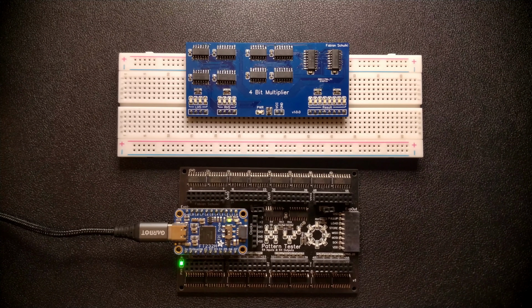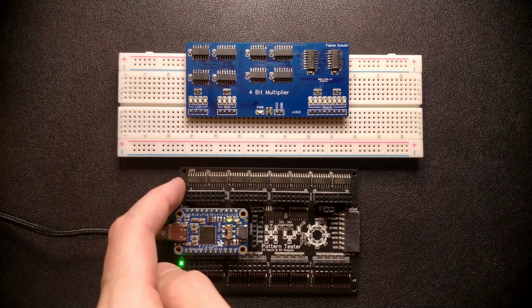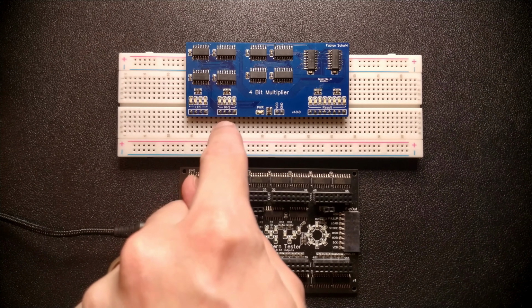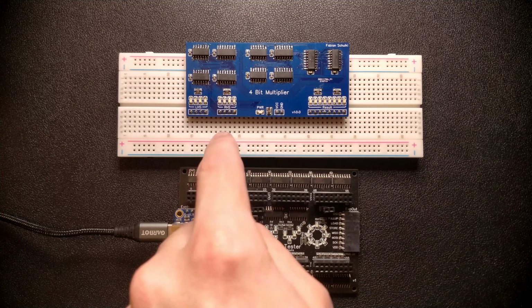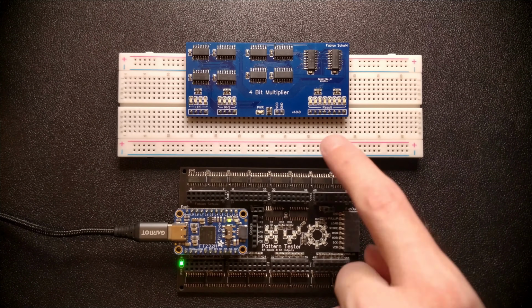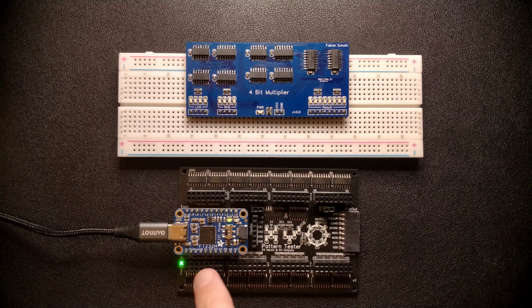So I think what we want to do is hook up the tester outputs here to the left-hand side and right-hand side inputs, such that we can apply different values to this multiplier here. And then the result as it comes out of the board, I think we want to bring that down to one of the inputs, such that we can read back the value that this board produces in the Python script that we have and actually check whether it's doing the right thing or not.